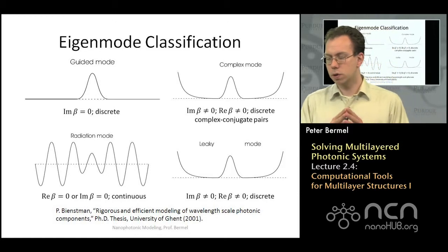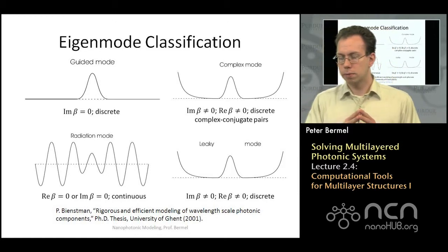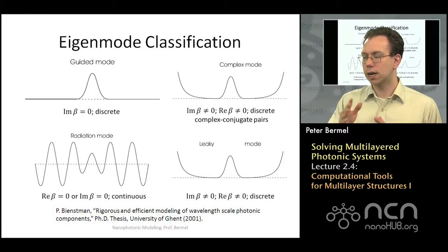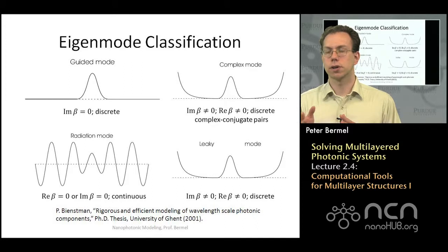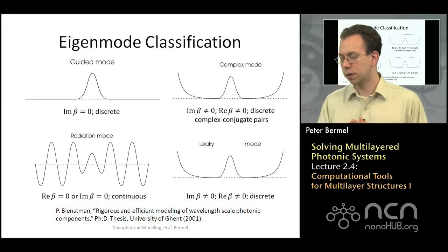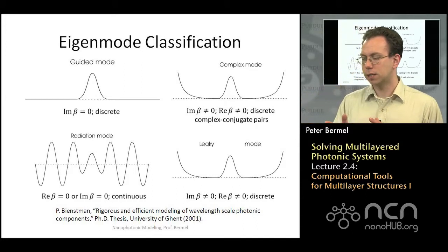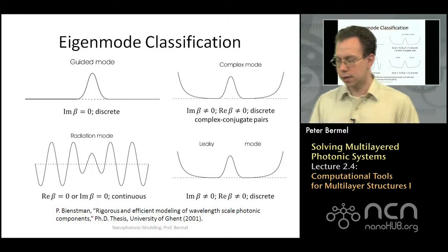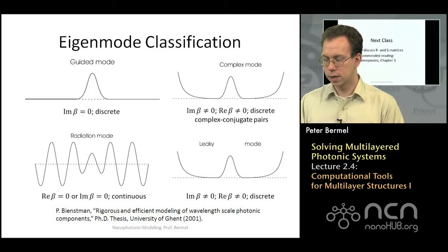That kind of mode may propagate very strongly in some cases, or may be reflected just through refractive index-based effects, but not resonant effects. Whereas the guided modes and leaky modes all interact strongly with resonances and are usually very well defined and only happen at certain frequencies. Radiation modes can happen at almost every frequency. So that's the key distinction.